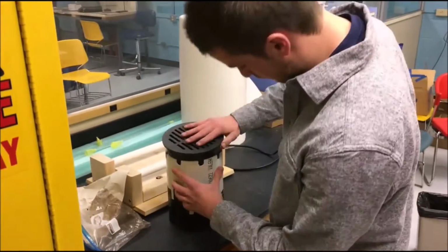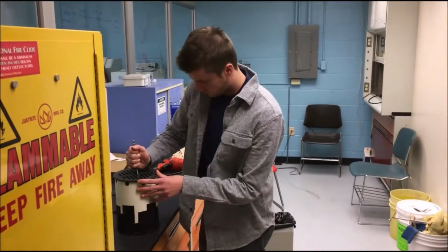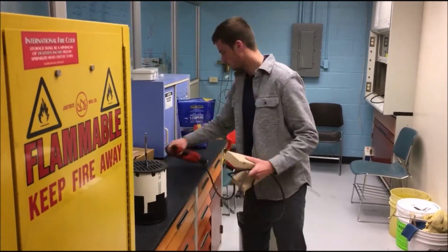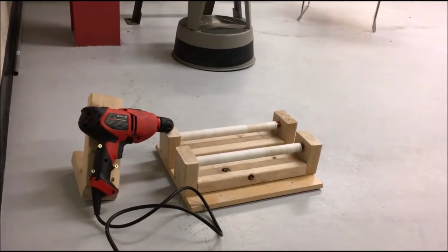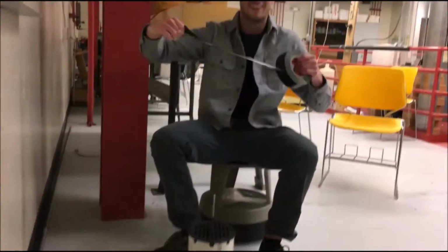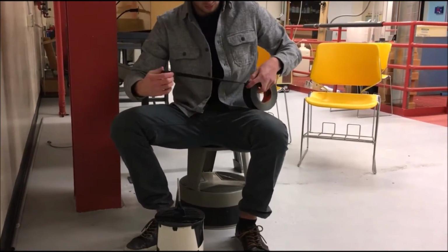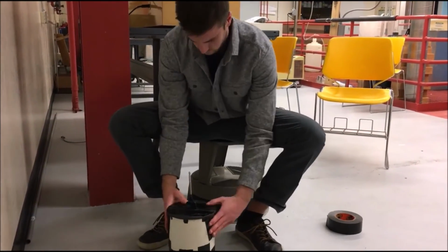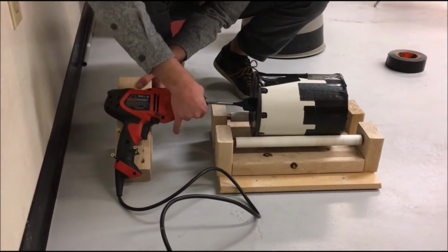Okay, after we pour the beans into the ball mill, we proceed to set up the equipment for the experiment. Now, while Nate's setting up this experiment, I'm going to be talking about safety. Safety is a key factor to this experiment. While the ball mill is running, all team members and anybody around must be wearing safety glasses. Additionally, there are many pinch points while the ball mill is operating, so we must wear industrial gloves while it is operating, and this is just to ensure safety of us and anybody around.